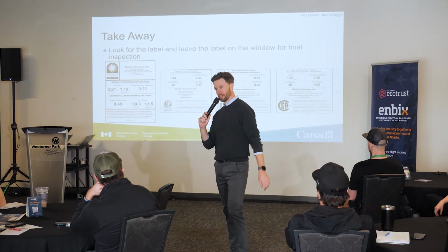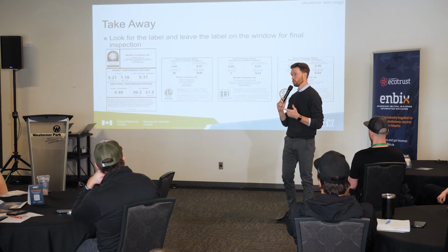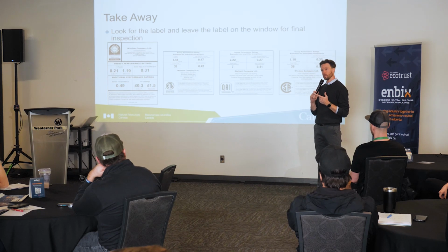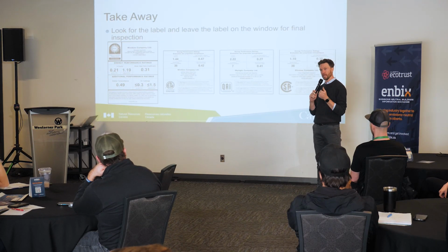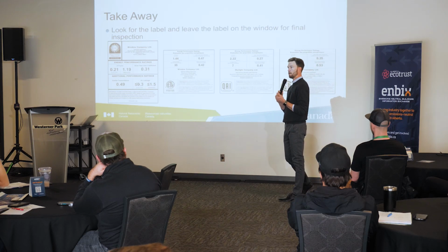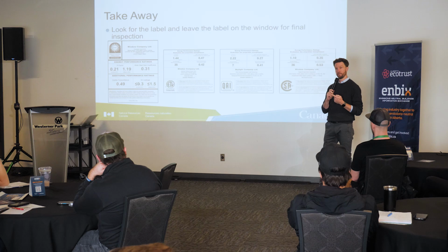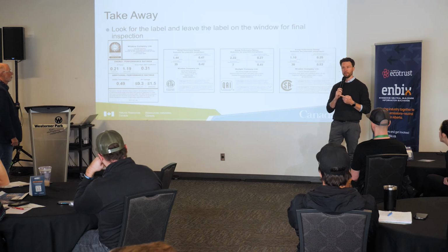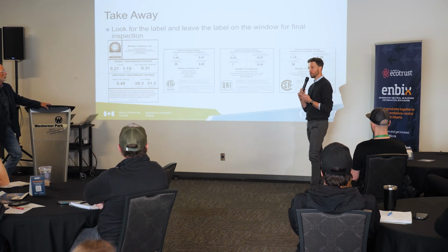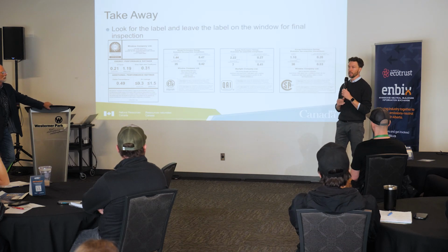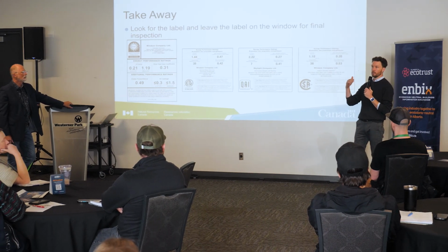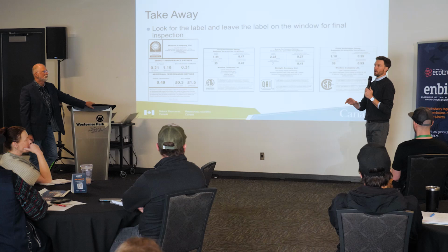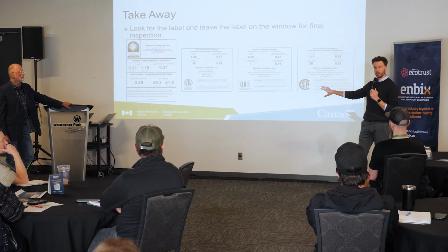From many resilience perspectives, including hail, but really with regards to wildfire, the requirements are now asking window manufacturers and window purchasers to consider tempered glass for the exterior pane, ideally, and a frame material that's not vinyl. Vinyl is by far the most common window material in our industry, but it just doesn't hold up to heat when you're exposed to wildfire. So unfortunately, the recommendation at the moment is a metal protected wood frame window with a tempered exterior glass layer. You can achieve all of these performance values with that window.